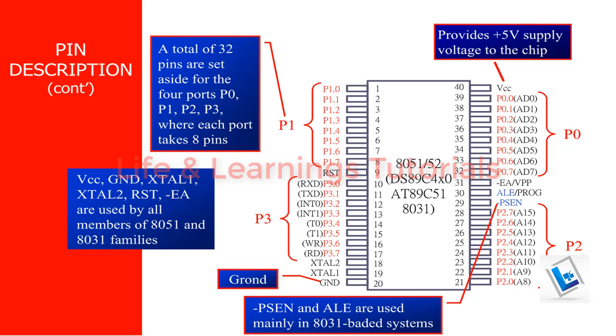Pin number 9 is a reset pin, which is normally used to reset the microcontroller, and there is no other function of this pin. One push button and resistor capacitor arrangement is required at this pin to reset the microcontroller properly.